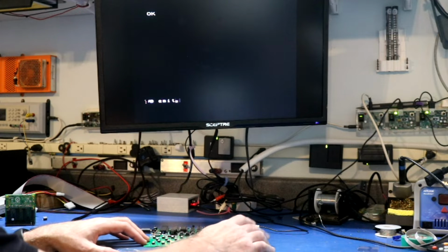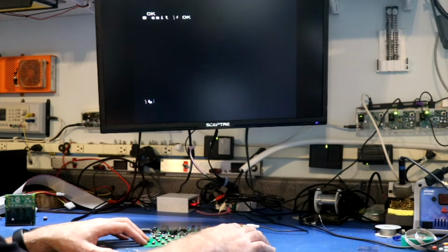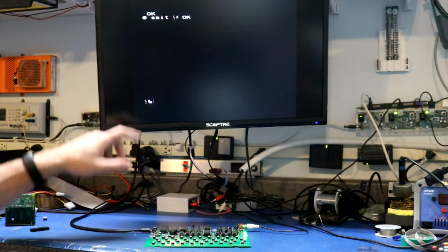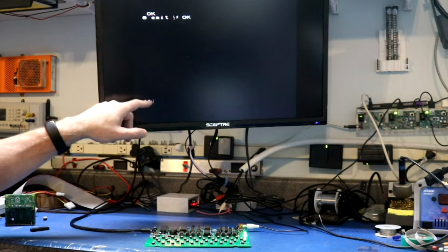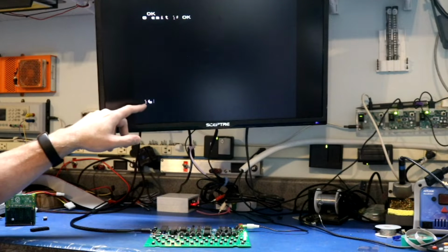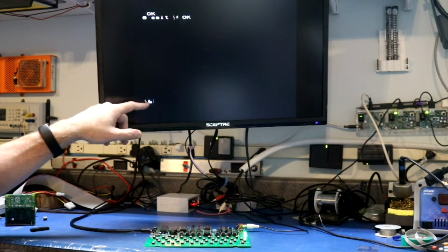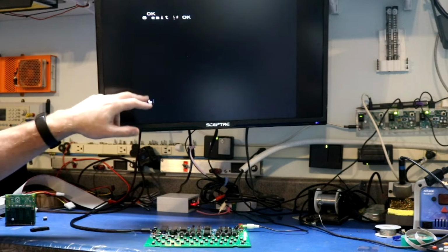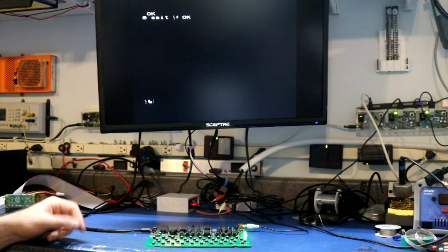So if I do a 0, let's see if this will actually work. Emit. We can probably get another one. Yeah, see, there he is. There's this 0. It sits right next to where you're typing in, and it has that null character. That null character should be blank, but on reboot, the character generator RAM is getting set with some kind of weird random value in there.